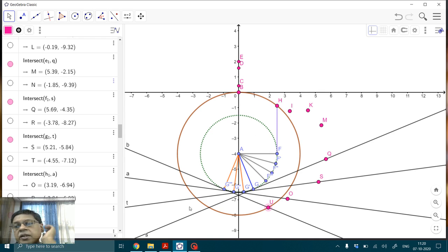All right, so to summarize, we start off by constructing this FH, which is root of RP square minus E square. Then for each of those tangents, F prime I is obtained by adding to FH the lift that I have. So that locates the trace point there. Similarly, this will be at 15.72, which is along this F double prime K. And the last one along F triple prime M, which will be 20 millimeters plus FH. So effectively, the distance along the tangents will be root of RP square minus E square, the base starting point, plus the lift, which is y of theta. So you will mark those points along that distance.